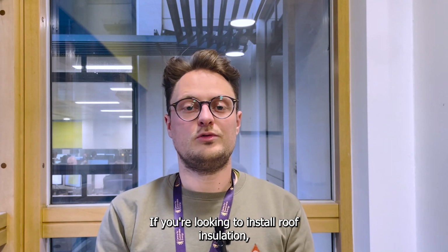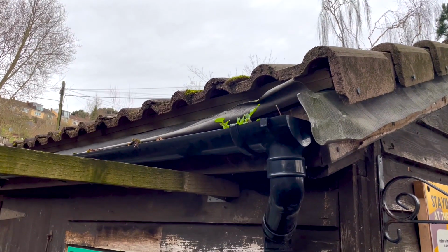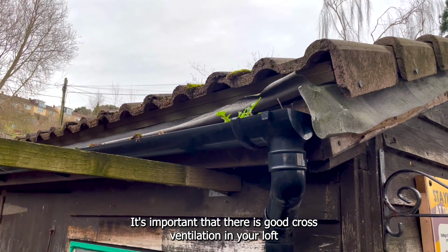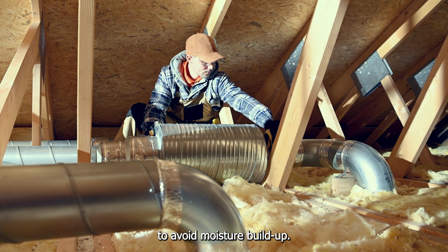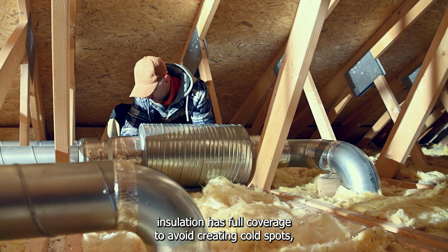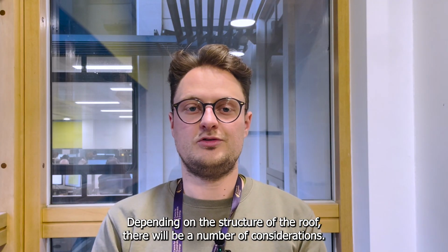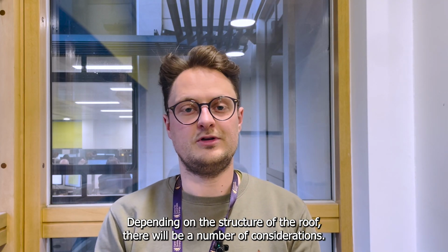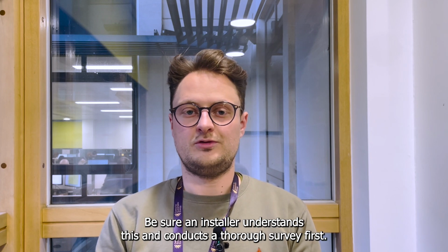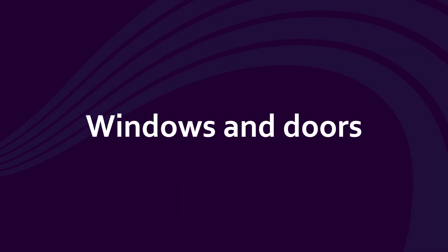If you're looking to install roof insulation, you need to ensure that your roof is in good condition and dry. It's important that there is good cross ventilation in your loft to avoid moisture buildup. An installer should make sure the loft insulation has full coverage to avoid creating cold spots, so don't forget to cover the loft hatch. Depending on the structure of the roof, there will be a number of considerations. Be sure an installer understands this and conducts a thorough survey first.